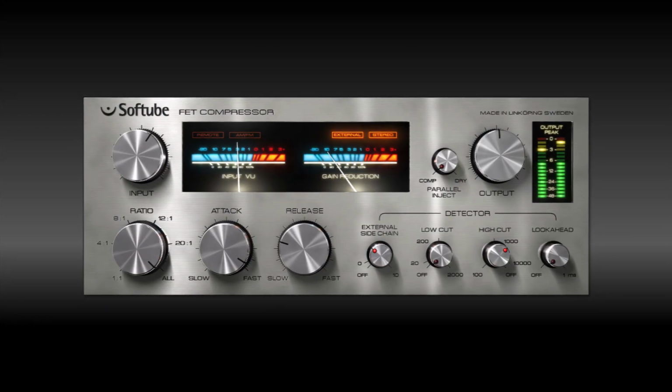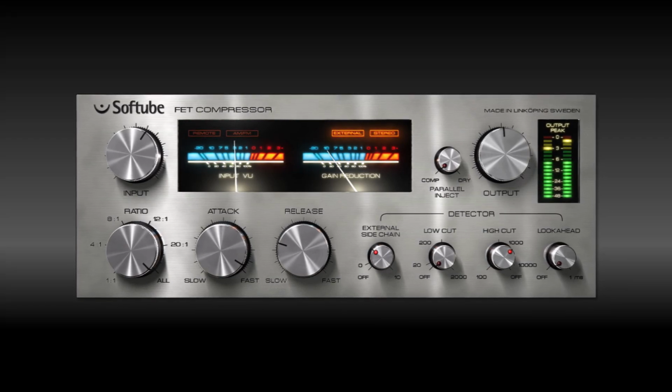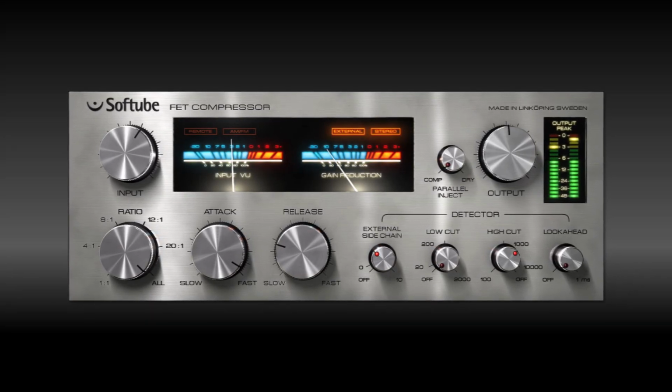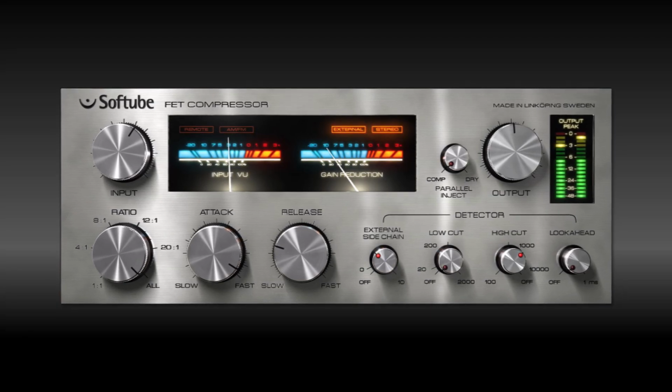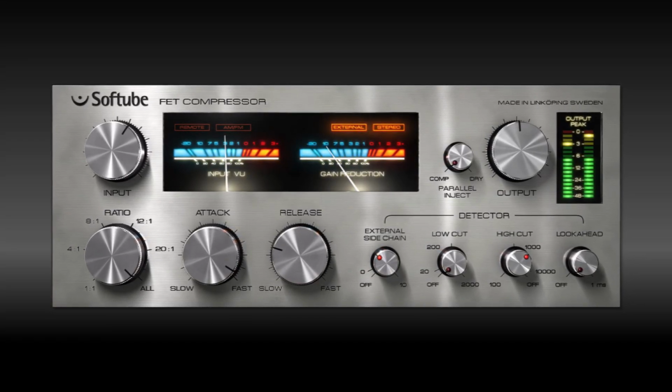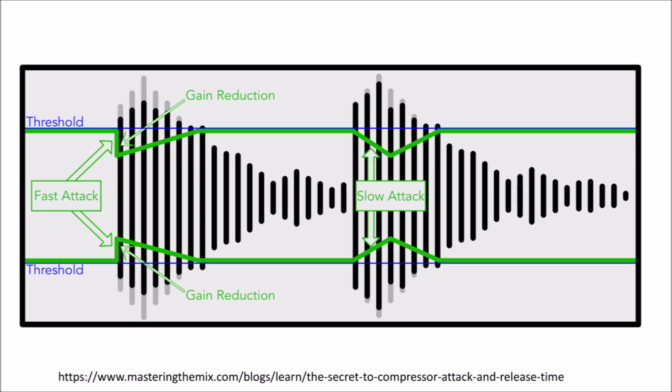For your run-of-the-mill compressor unit or VST plugin, meaning it does nothing else to the signal except just compress, you'll often find some common controls exposed to the user. Sometimes they're hidden, sometimes they're baked into the circuit, but for ones with more or less everything exposed to the user, you'll see a threshold control, just like the threshold we talked about with distortion, where anything above that threshold, instead of being clipped, gets attenuated. So, say you have a threshold of 0.8 volts, well, then that 1 volt signal will get attenuated to 0.8. It does not make the entire signal quieter, it just makes that peak quieter.